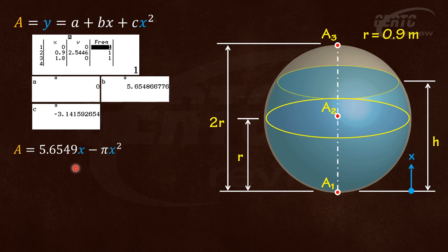To solve time rates, we will use the formula Q equals A times V. A is the cross-sectional area of water at any depth. So if you have the power to compute the area at any depth, then you can easily use that formula. Whether the water is going out or going in the tank, then no problem. Okay, what's the other application of that? Hydraulics.